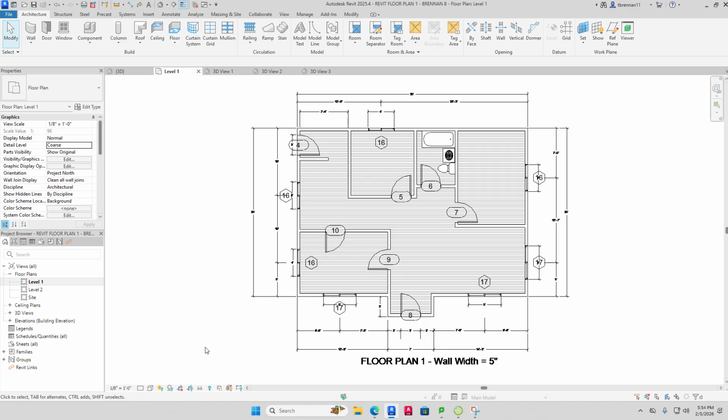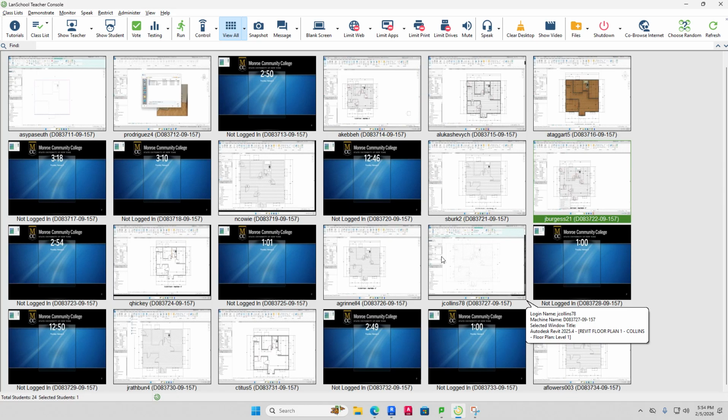So you want to go down here and click on the glasses, and go to Reset Temporary Height Isolate right there, which is at the bottom. And when you do that, you'll then be able to see your floor again. So you should have that.